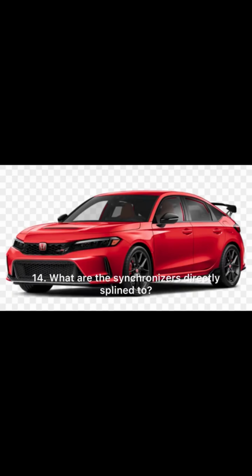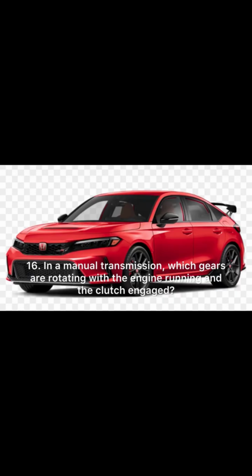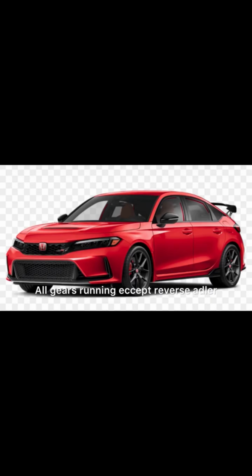14. What are the synchronizers directly splined to? The output or main shaft. 15. How are gears locked to the output shaft? Through the synchronizer's sleeve and hub. 16. In a manual transmission, which gears are rotating with the engine running and the clutch engaged? All gears running except reverse idler.